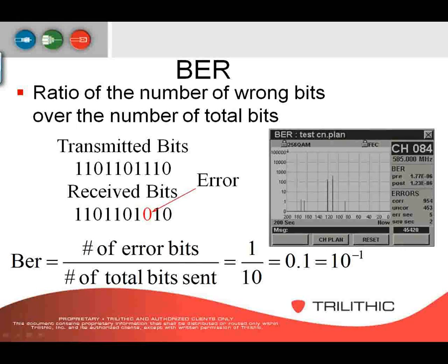Bit error rate measures how often symbols are pushed into the neighboring symbol territories, causing these symbols to be misinterpreted. Remember I talked earlier about how whenever a bit falls outside of the decision boundaries, it cannot be interpreted properly. That's what adds to your bit errors.